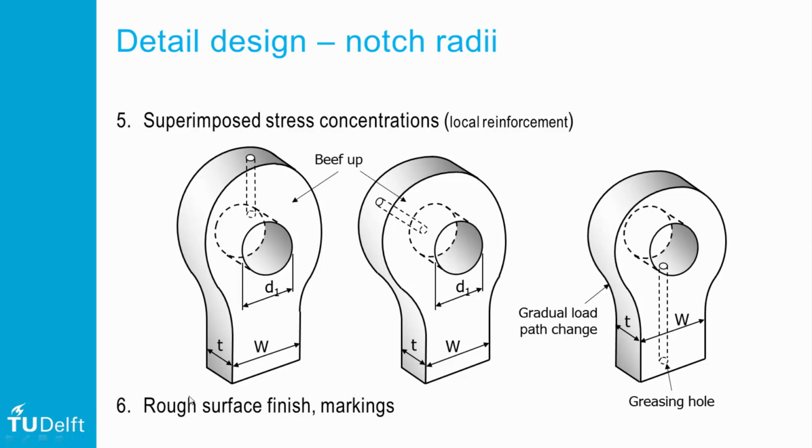Last, pay attention to the surface. Rough surfaces or surface markings created by machining, for example, easily increase stress concentration factors, resulting in fatigue crack initiation.